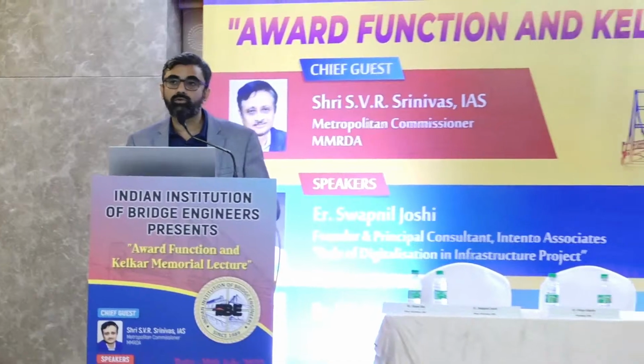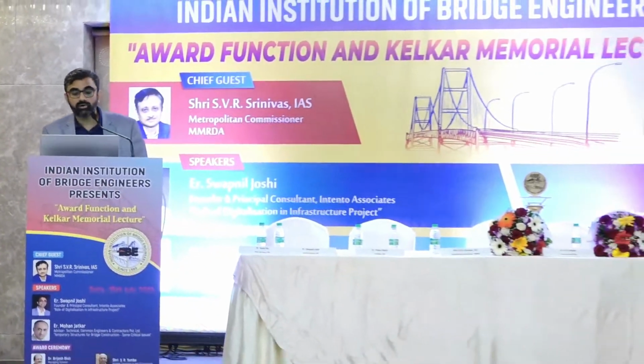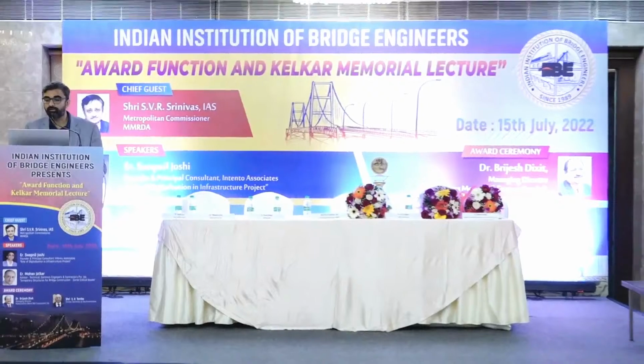Then we have focused on something called smart modeling, because the quantity takeoff and other things which I have shown were normal. But what we have done to improve the time cycle of implementation is we have explored this model where we can extract the coordinates for the cable profile as well as the shuttering coordinates. We were extracting the cable coordinates and the shuttering coordinates directly from the model itself. So it has saved a huge amount of time at site. You need not have a team dedicated to pull out those pointers or coordinates at site. This is one smart modeling which we have done.